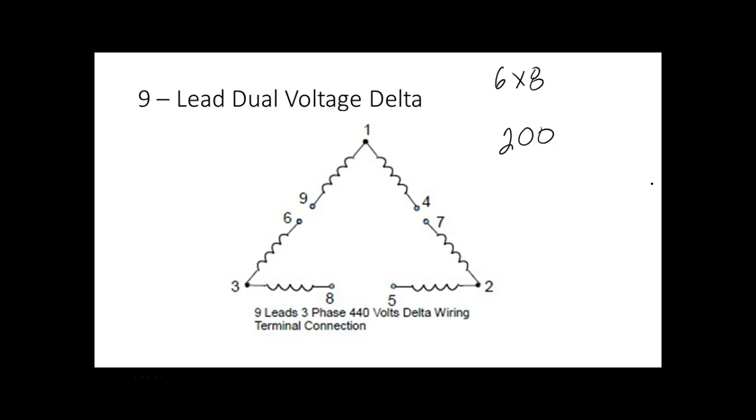So these big horsepower motors, we usually try to do one of two things. What you can do on a variable frequency drive is you can put a ramp up there. You can say, okay, I want this thing to accelerate from 0 all the way up to 1,700 RPM at a certain slant. And what it does, it deliberately reduces the torque of the motor when you start it up.